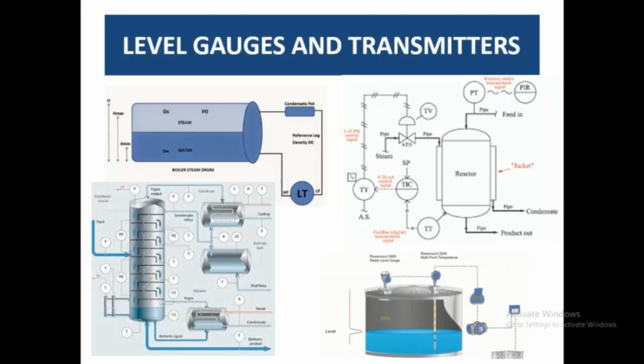The only method to understand and rectify how much mass is accumulated in your process is to know all the specs of your equipment, their diameters, heights, and complete specs. After that you need to know the running parameters like temperature, pressure, level transmitters, and the flow meters. So in a vessel you can easily calculate the accumulation mass, as I explained for the steam boiler.